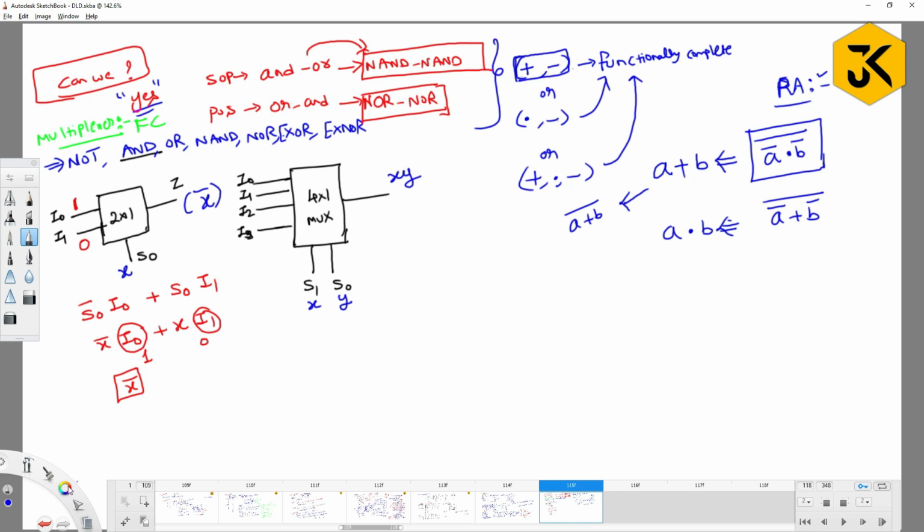If you construct the truth table for this, with S1, S0, it looks like this: 0, 0, 0, 1, 1, 0, 1, 1, 1, 1, 0, 0, 0, 1. These are the inputs. So the inputs are 0, 0, 0 and 1. If I pass three zeros followed by 1, and here I pass the value 1, 0, what is the select line going to select?